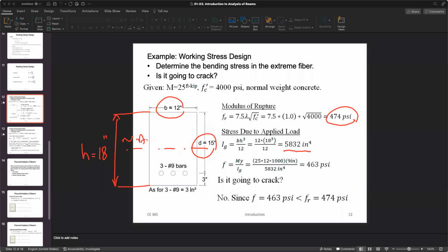All right, so before continuing, just quickly, what's going on with that D concept here. All right. This D is effective depth. Effective depth. So this D really means the height from the top of your section to the level of the tension reinforcement.